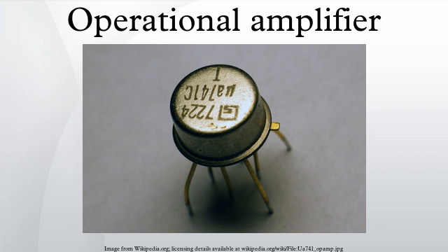Applicability considerations. Note, while the 741 was historically used in audio and other sensitive equipment, such use is now rare because of the improved noise performance of more modern op-amps. Apart from generating noticeable hiss, 741s and other older op-amps may have poor common mode rejection ratios and so will often introduce cable-borne mains hum and other common mode interference, such as switch clicks, into sensitive equipment. The 741 has come to often mean a generic op-amp IC.